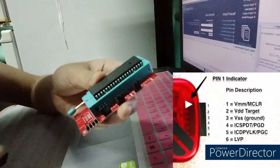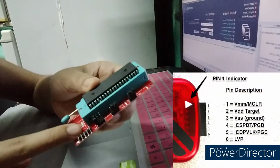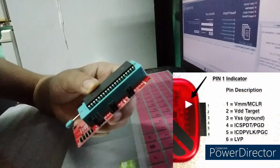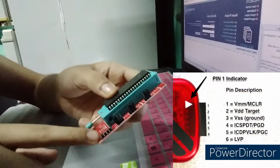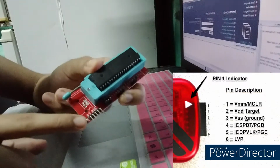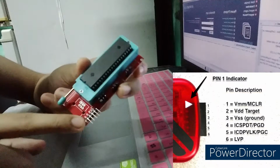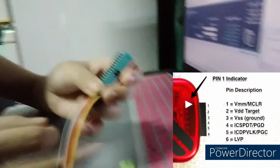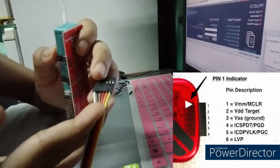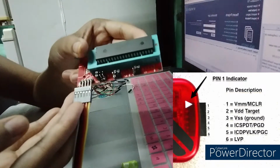Just to explain, the first pin of our Microchip adapter is our MCLR pin, and then the next pin will be VCC, or our VDD. The next pin will be ground or our VSS. As you can see here, it is labeled. And then our fourth pin is PGD and our fifth pin is PGC. Those pins will be connected here. So the yellow wire here is our MCLR, and you just have to connect the pins here correctly.